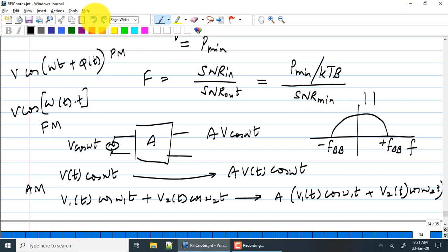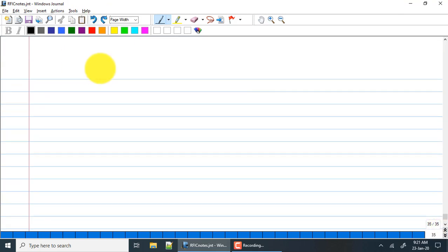So now, in our equation, because I am trying to find out P min, I need to use the value of the SNR. If the SNR were not minimum at a particular value of P, that means I can actually go down lower. Right? What will happen is if I am reducing the power at the input of the receiver, the output SNR will keep dropping. The bit error rate will continue to increase till it hits the limit. That limit will hopefully happen at SNR min.